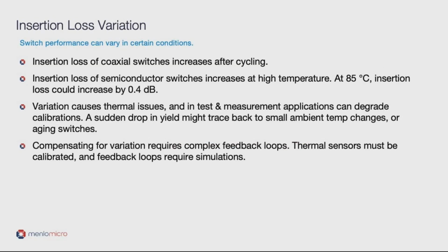The last specification we'll discuss today is insertion loss variation. Insertion loss variation describes the changes in insertion loss that can happen over temperature or the lifetime of the system. For example, with coaxial switches, the insertion loss will typically increase over the lifetime of the switch. This is caused by the mechanical wear of the contacts inside of the switch.